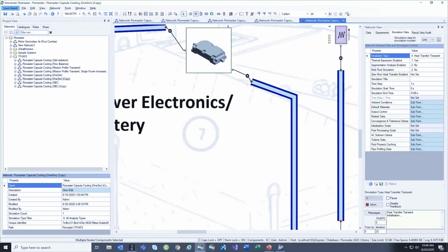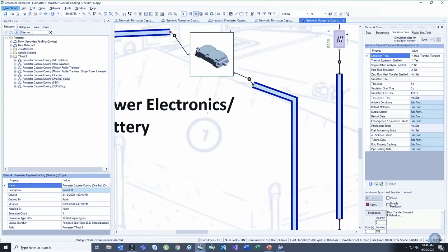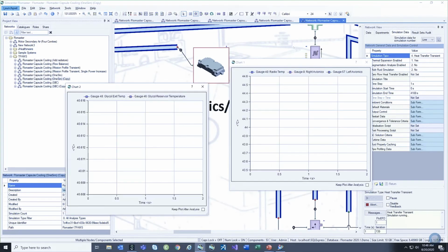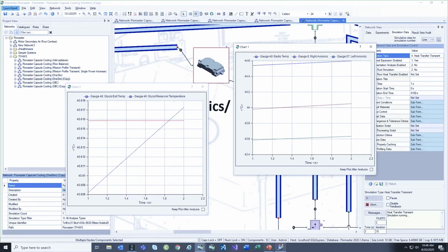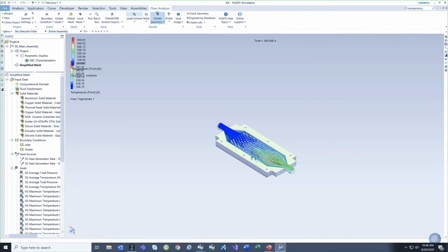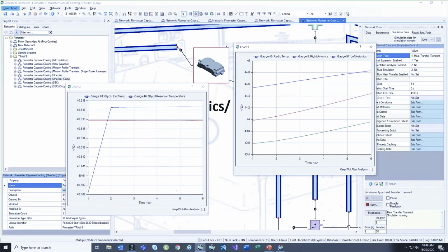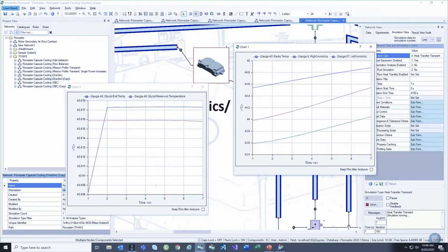But when I run the simulation, something different is going to happen. It's going to look like we're running directly inside Flowmaster. But what we'll see here is another iteration counter for Flow ESD. And what's actually happening is this entire model, the whole matrix solved for the 1D model, is being embedded within the external Flow ESD solver. And everything is being run from within Flow ESD as if Flowmaster were the boundary conditions extending outside the 3D geometry, because that's precisely what we're doing. We're marrying those boundary conditions between the two models and linking them together in a single solve.